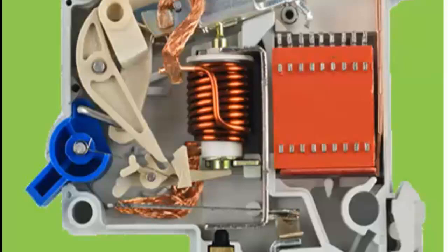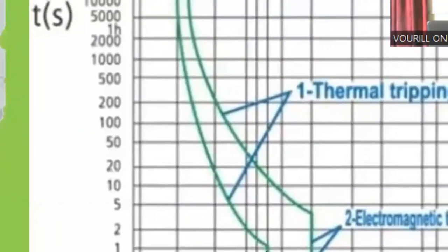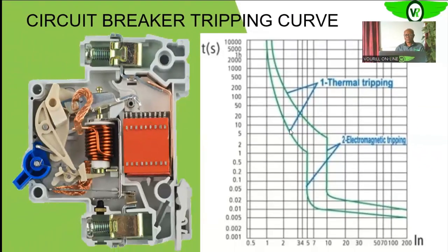and that is what is represented by this part of your graph. So if the circuit breaker is in a circuit that is operating within its nominal current rating, you'll see that it will be operating within this region of the trip curve of this graph.